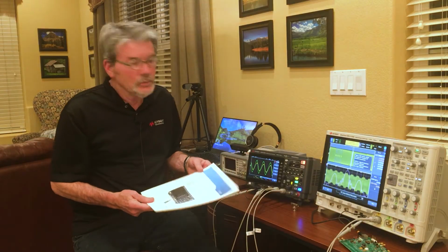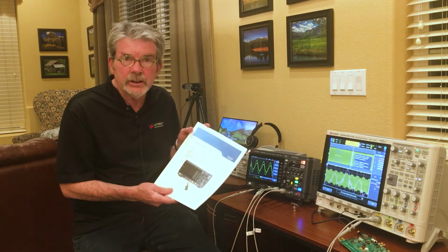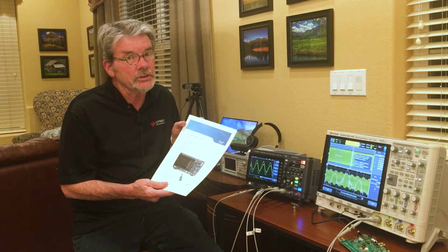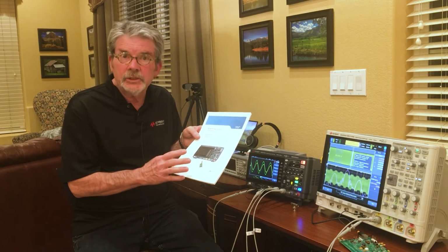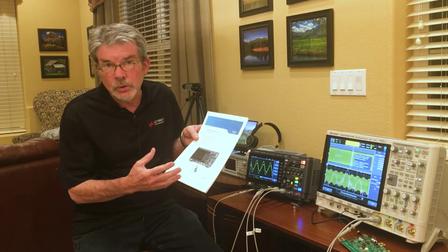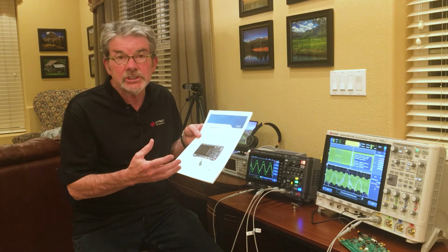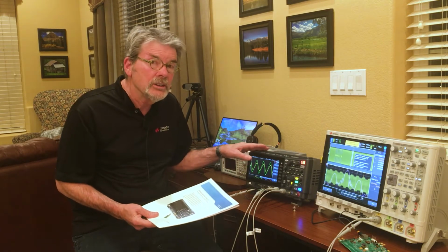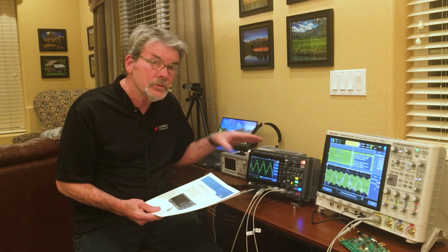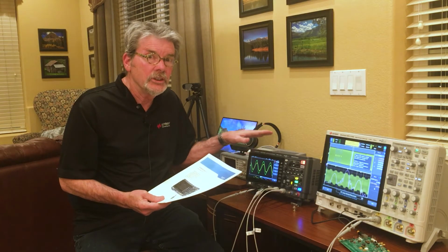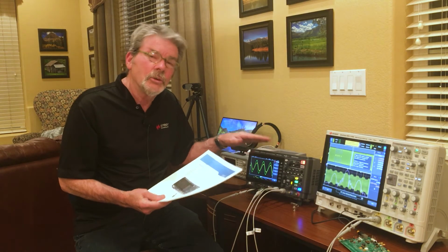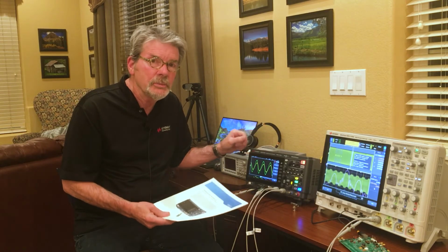Now, also included in addition to the training board, is a very comprehensive tutorial and lab guide. It was written specifically for engineering students. The first part of it gives a lot of theory, talks about transfer functions, poles and zeros with some fill-in-the-blank questions and answers, and then it gives step-by-step instructions on how to perform both manual Bode plots using an oscilloscope, the way most students are doing it today, as well as automatic Bode plots using the automatic capability that's available in InfiniiVision oscilloscopes. Let's now go ahead and perform a Bode plot measurement on this bandpass filter.